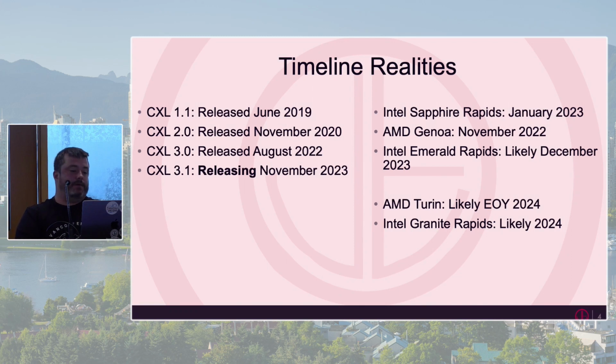Why are these significant? Because these 3 CPUs at the top, the Sapphire Rapids, Emerald Rapids, and Genoa, all launched with CXL 1.1 support. So all of those cool whiz-bang features in CXL 2.0 and 3.0 and 3.1 that look really cool on the CXL consortium slides aren't in what we have today, aren't even close. And like Srijit also alluded to, it's CXL 1.1-ish. Depending on which CPU vendor you actually work with, depends on what the definition of the ish is. And so that's mildly frustrating.